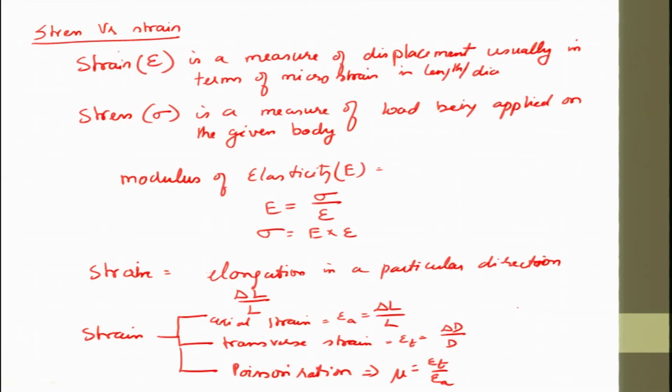If we can measure the change in resistance, because that is easy for me to process and later use for control, because it is voltage as the output. So, I now try to measure the resistance which is getting generated or a change in resistance. For that we use a device called a strain gauge.